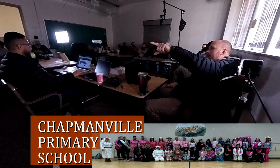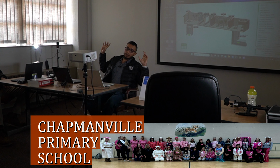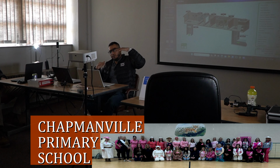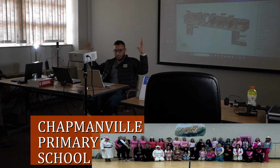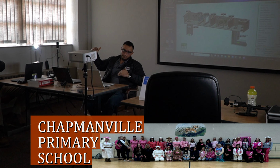Well, that's what he's saying. He wrote a program to show the return value. So if your values aren't the same, potentially one of your damper motors might be bad. Well, you don't have two damper motors. There's only one. One opens, the other shuts. So whatever the outside damper is, the return will be the subtraction of it. If we have 100% total of the volume of the air, and you are 70% on the outside, that means you are 30% on the return. Vice versa, right?